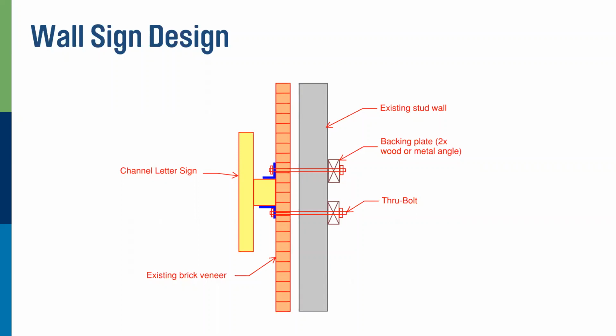That's why it's called dissimilar metals. So you can use stainless steel. Stainless steel is inert, it won't react with the aluminum. Or galvanizing. Galvanizing is a coating of zinc. So hot dip galvanized is also a protective coating that works with aluminum. So just by design, because of these special elements, if you use stainless steel or hot dip galvanized fasteners, you don't have to worry about it. It will work with aluminum also.